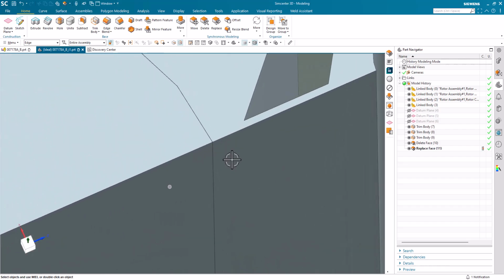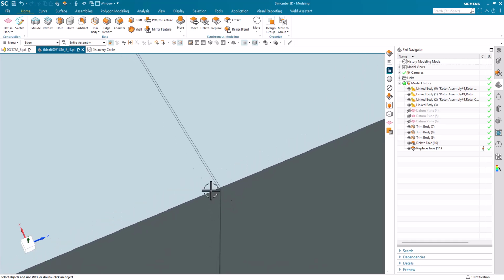And then if I just zoom in on this area just to highlight that I do have overlap in the geometry. So the face of the rotor is larger in diameter than the cylindrical face of the shaft, or rather the shaft is larger than the face on the rotor. And so in this analysis, I've got this press fit, and I'm building the overlap in the geometry. So I can also have those flush, and I can have offsets defined in my contact and in the solver.